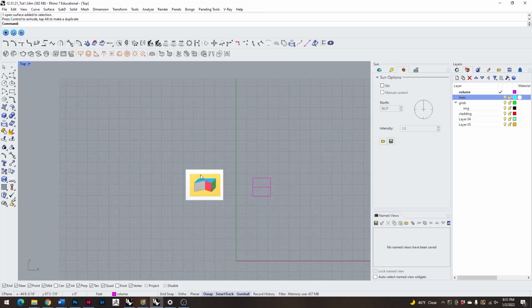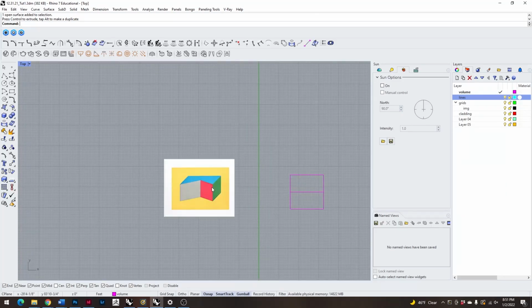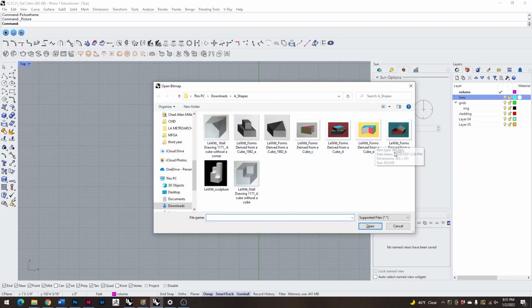The next step is, once you've selected or been assigned your painting from which you'll create a 3D geometry, you'll load that into your Rhino document using the picture frame command. And these are all the different volumes.